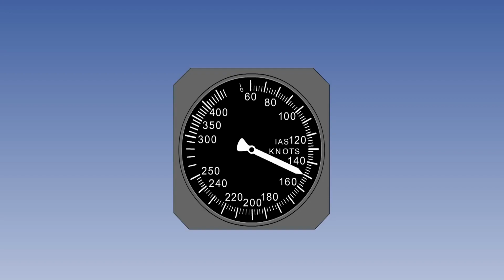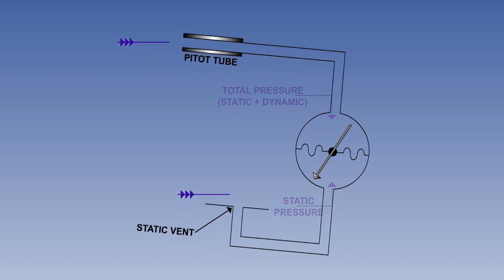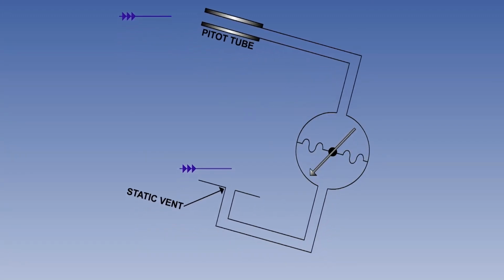There are, perhaps rather confusingly until you are familiar with them, several different categories of airspeed. The simplest is the indicated airspeed, IAS, which, as its name implies, is the airspeed shown on the ASI. Calibrated airspeed is an accurate measurement of the dynamic pressure of significance when the aircraft is flying slowly. The position of the pitot tube and static vents, and the aircraft's undercarriage and flap position, or configuration and attitude, will all affect the pressures that are sensed, particularly those at the static vents. Under these conditions, a false dynamic pressure will be sensed, resulting in a false IAS display.